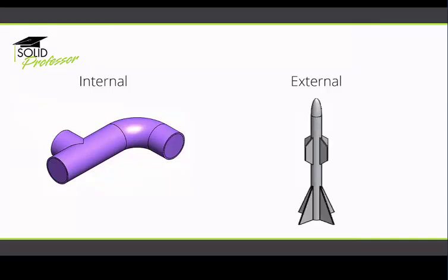An external flow analysis is one where the fluid flow surrounds the model, for instance a flow around a vehicle, rocket, or other projectile. If a flow has both internal and external elements, like the flow through a car with the windows down or flow through and around a building, for instance, then you should treat it as an external analysis. For external analyses such as these, you must set up a computational domain boundary, or an area around the model for which the flow is calculated. We'll look more at this in the external analyses sections of this course, but for this section, we'll look at the two aspects of model preparation for internal studies, lids and check geometry.